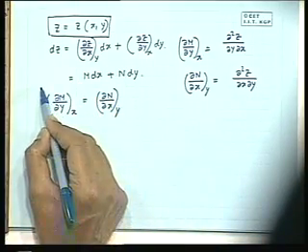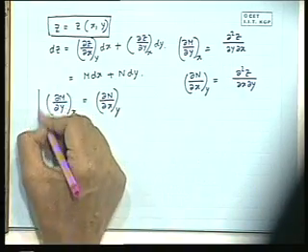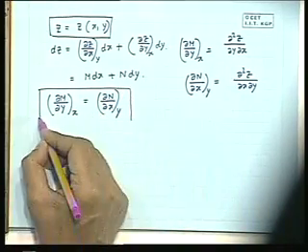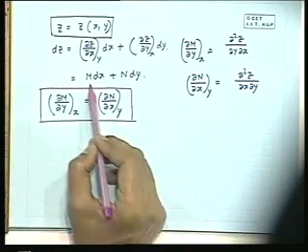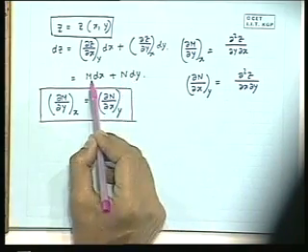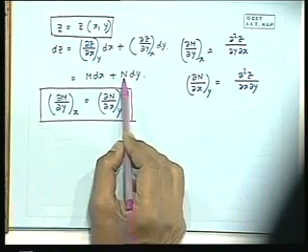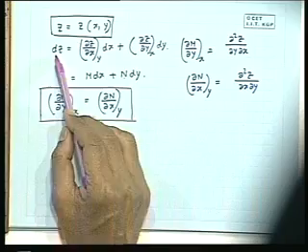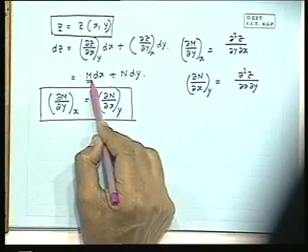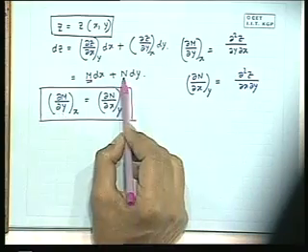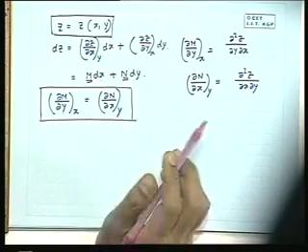This is one of the very important relationships in mathematics, used in deriving some important thermodynamic property relations: if dz is expressed as m dx plus n dy, where m stands for the differentiation of z with respect to x at constant y, and n stands for differentiation of z with respect to y at constant x, then the differentiation of m with respect to y at constant x has to be equal to the differentiation of n with respect to x at constant y.